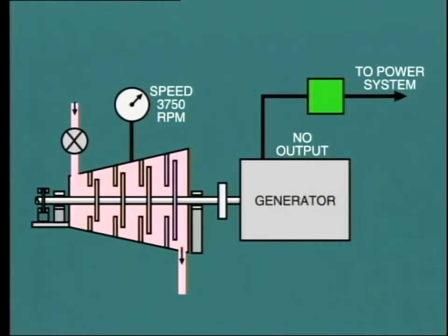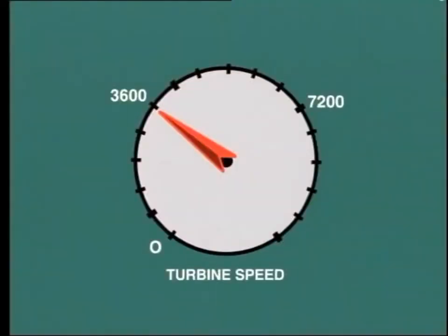Under normal circumstances, the governor should be able to close the turbine control valve sufficiently to bring the speed close to normal within a few seconds. However, imagine what would happen if the governor failed to act properly, or the power piston seized, or some other defect prevented movement of the control valves. In this case, steam flow to the turbine would continue, with the result that the speed would rapidly rise to 2 or 3 times normal.